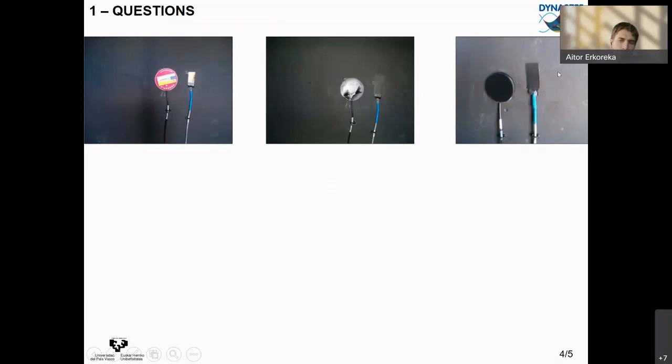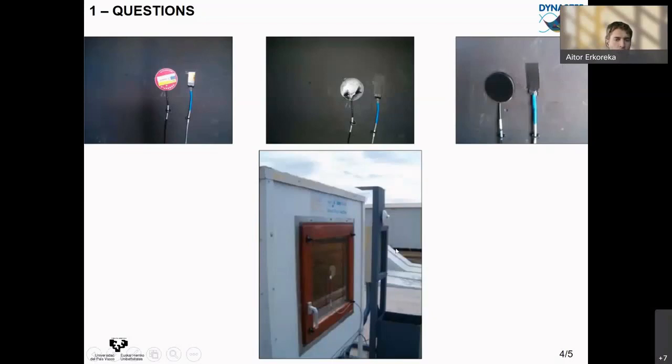So this surface and this sensor will only have the same temperature when the emissivity of these two surfaces for both the long wave radiation and the solar radiation, that is the short wave radiation, are similar. When we have windows, we have a problem, because this sensor will never behave as the real glazing.